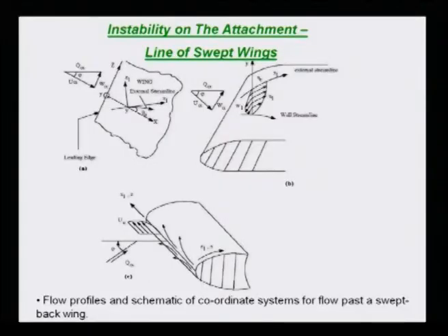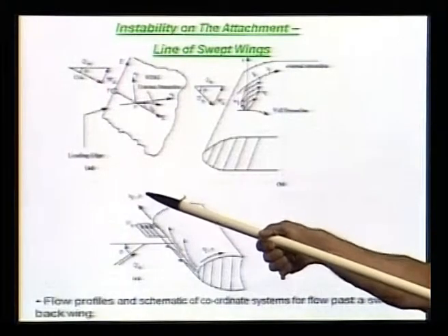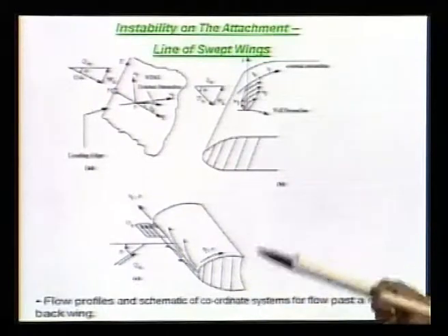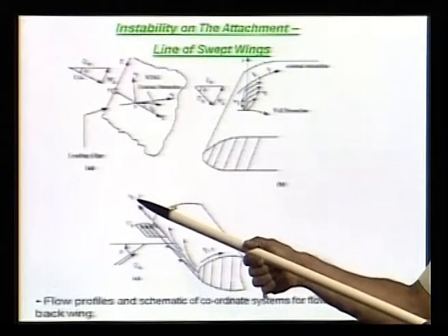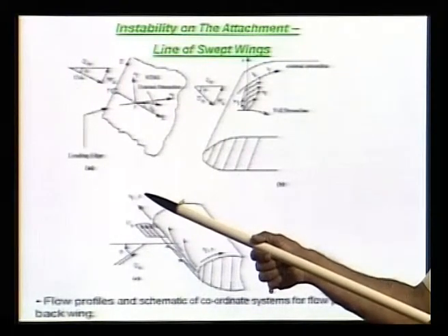X 1 is the external streamline fixed coordinate system. So, viewed from external streamline, that would be the x 1 direction, and from the wing fixed direction that would be your z direction, because that is the span direction, right. Basically it is a description that viewed from a geometric perspective that is the spanwise direction z, and viewed from the flow direction that is actually the streamwise direction. So, that is why you notice that we have called it simultaneously x1 and z, right.